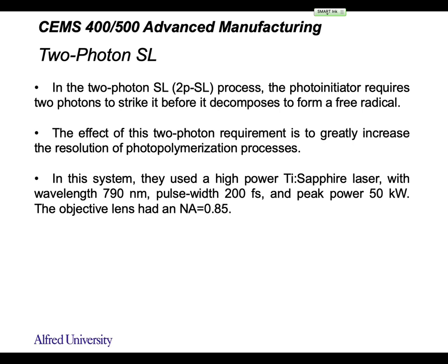You may argue that you can also focus your laser for your macro stereolithography, right? We just spent some time on that. The difference for the focus laser of 1 photon polymerization is that you have to focus on the surface of your resin, right? You have to focus on the surface of your resin. If this focus spot is in the middle of this resin, this area will be gradually solidified, right? Because they have 1 photon absorption, rather than 2 photon absorption.